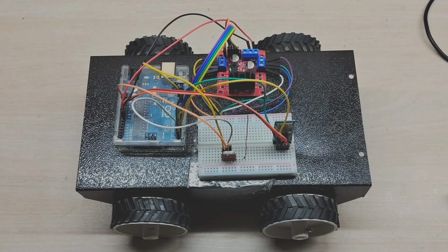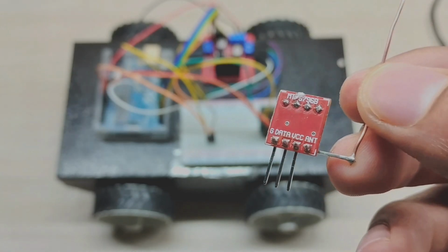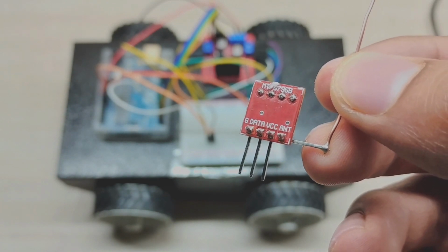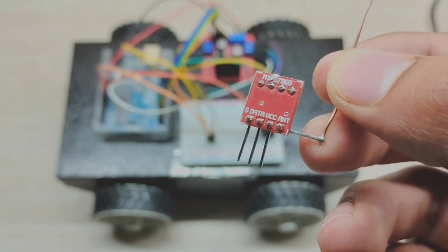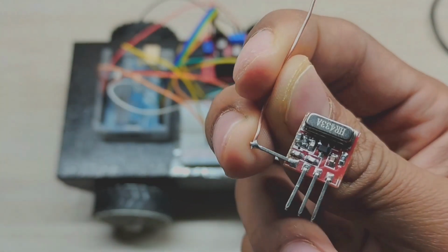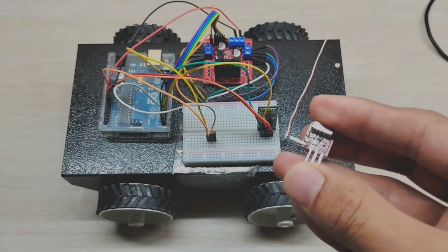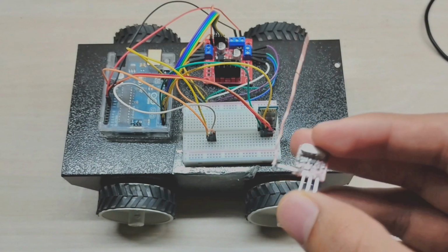In the previous task, 6.1P, we ended up making a Bluetooth car. Now to make a robotic swarm, I used the RF module. It consists of two components, one is a transmitter and another is a receiver, which are used in the master and the slave car respectively. This is a transmitter. As you can see, it contains 3 pins, which are the ground pin, data pin and VCC pin, and another is the antenna pin, which transmits the signal to the receiver.